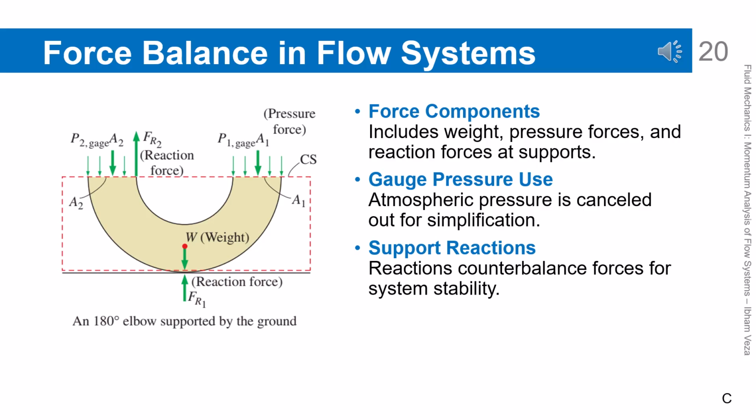Force balance in flow systems. In flow systems, the total force usually consists of weight, pressure forces, and reaction forces from supports. To simplify the analysis, atmospheric pressure is eliminated by using gauge pressure. The reaction forces from supports appear to balance the forces caused by the flow. All these forces are then related to the change in fluid momentum. With this approach, the forces acting on pipes or fittings can be computed systematically.